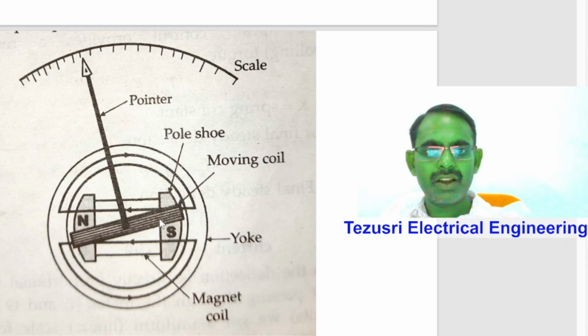The active sides of the moving coil are located in the uniform radial field between the pole shoe and the steel yoke. Because of this arrangement, the PMMC meter is unaffected by external magnetic fields and also eliminates the magnetic shunting effects in steel panel constructions.